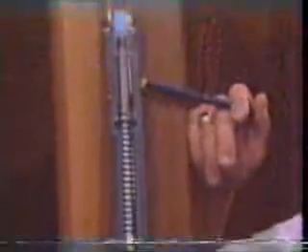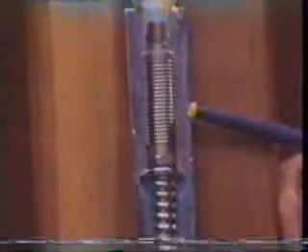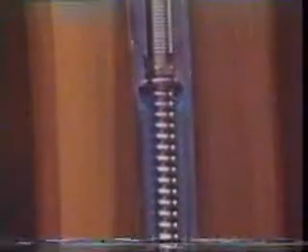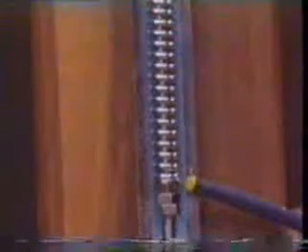Going back to the bellows section, in this particular valve, this bellows is never charged with nitrogen. However, some vendors have the capability of adding nitrogen pressure to the bellows in order to operate at higher pressures. In this particular valve, the spring is the only pressure calibration device, and by increasing the load on the spring, we raise the pressure of the valve. By decreasing the load on the spring, the calibration pressure is decreased.